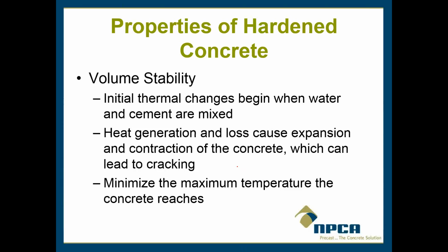Just another little tidbit. The heat generated during the hydration reaction can cause expansion and contraction. Initial thermal changes begin when the water and cement are mixed because that hydration reaction is exothermic. So all of that needs to be taken into consideration, but typically doesn't become a very large issue.